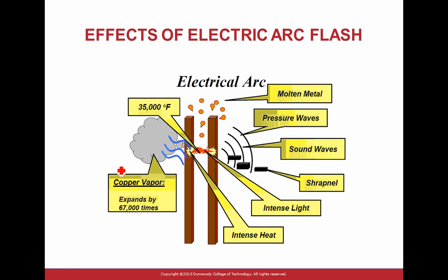Here's an arc flash, guys. Say something is dropped, it's not bolted. You drop something, it's a high impedance short between a ground and a hot, or a hot and a hot. So what's wrong with that one? Look at the amount of heat there. Now you've got yourself into a furnace.